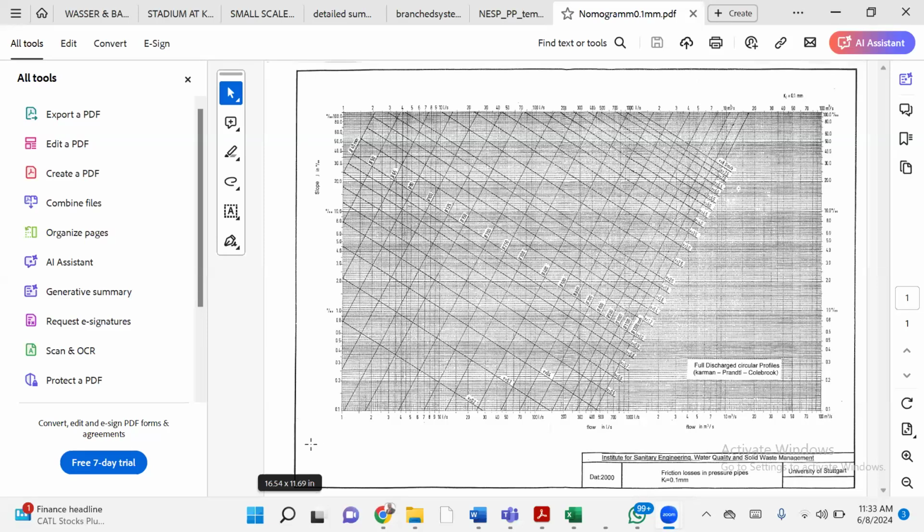And then the same thing applies to slope. If the slope is less than 0.1 per thousand, this slope is calibrated in per thousand. That's why it's 0.00. This is per kilometer. So if I say slope of 2, it means 2 meters per kilometer. Or if I say 2%, it means 2 per 100.